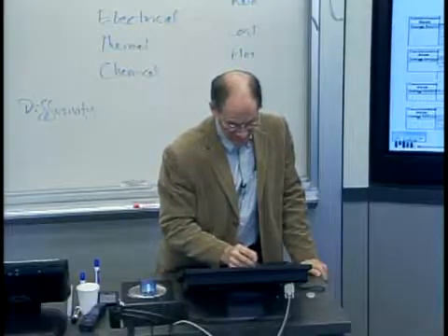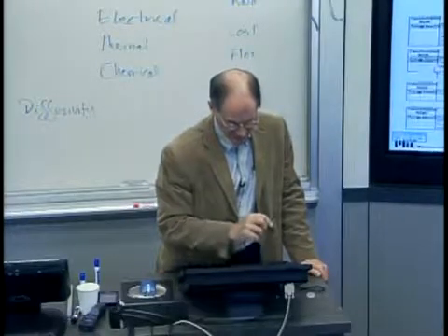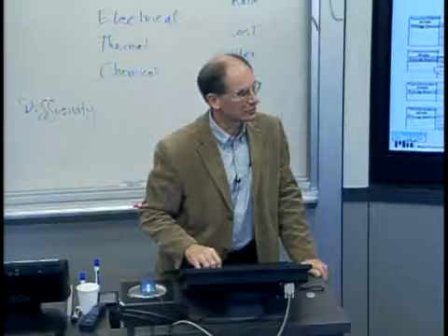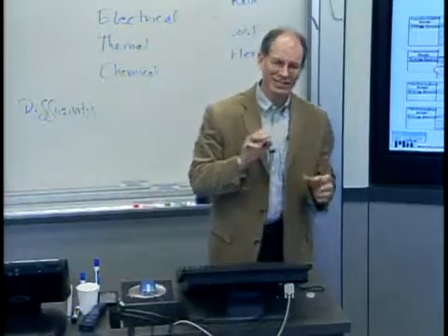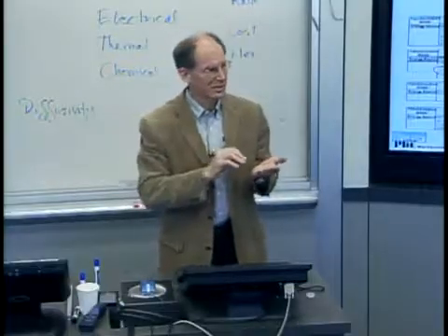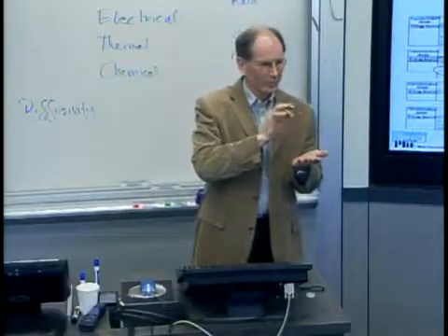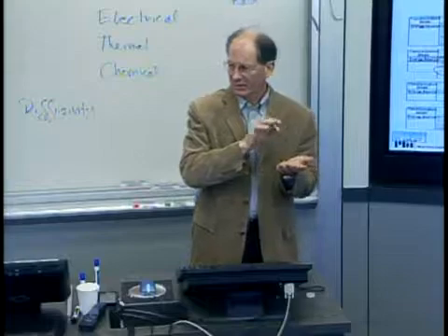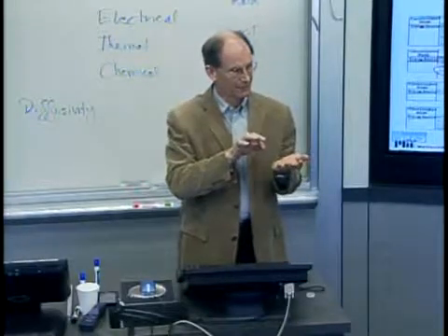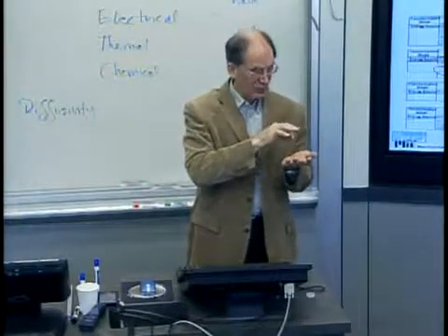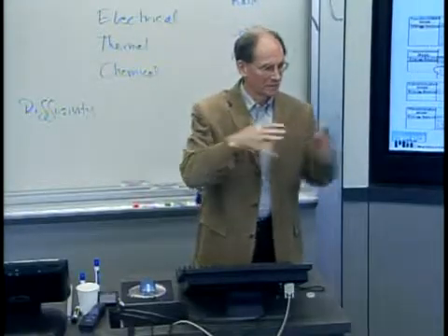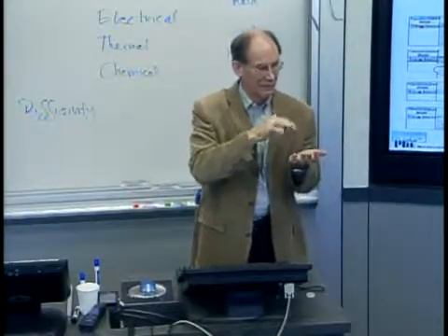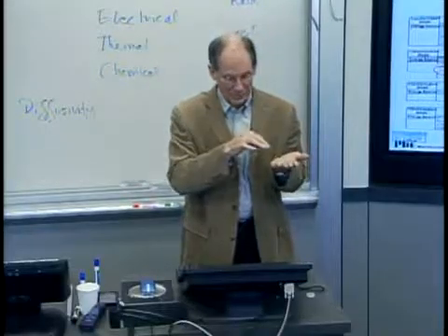Then Ellie Sachs at MIT invented this process called 3D printing. If you look at 3D printing, it's not exactly this, but it's essentially the same as saying I'm going to put down each piece of that powder one piece at a time. He does it by joining the powder one drop at a time. He puts a binder on it. Instead of binding it all at once, he puts a drop down at a time. It's an inkjet type process.